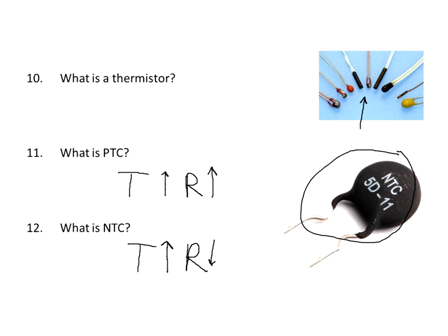What is a negative temperature coefficient device? Well, that would be a basic BJT transistor. When the temperature goes up, the beta goes up, which makes the resistance go down, and that makes more heat. And more heat increases the temperature, and the resistance goes even down further, creates more current, more heat. Eventually, it goes into what we call thermal runaway.